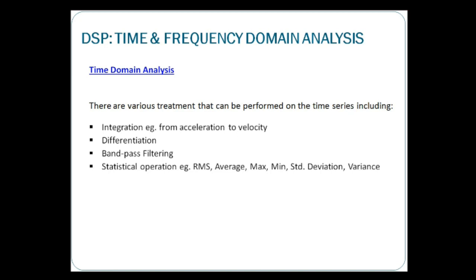So in the time series or time domain, these statistical operations can give us an idea of the overall vibration in terms of its RMS, maximum, variance or standard deviation. Basically, it gives us an overall idea of the signal strength, or the vibration severity, that we are capturing.